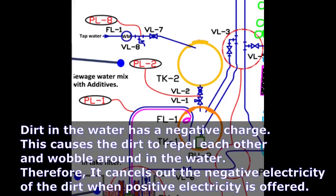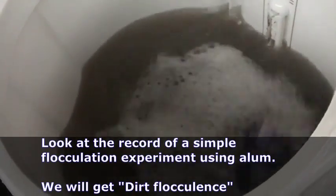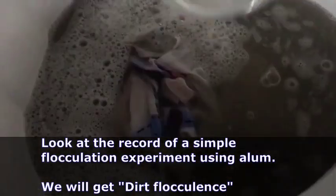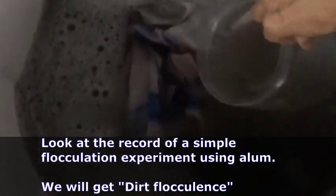Dirt in the water has a negative charge. This causes the dirt to repel each other and wobble around in the water. Therefore, when positive electricity is offered, it cancels out the negative electricity of the dirt. This causes dirt flocculants to form in the water. Look at the record of a simple flocculation experiment using alum. We will get dirt flocculants.